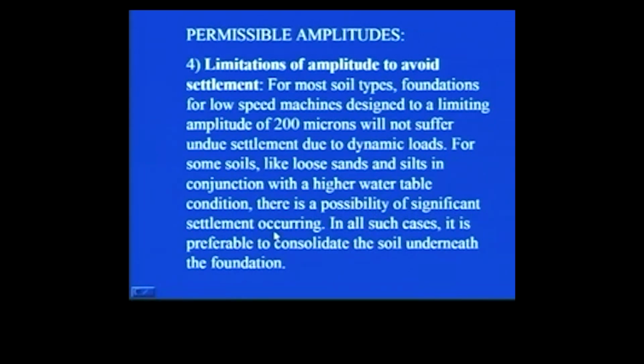Obviously, if the soil strata is loose or if the water table is present much near the ground surface, the settlements are going to be high. So, in all such cases, it is preferable to consolidate the soil underneath the foundation, such that the limiting amplitude which you get works out to be 200 microns.